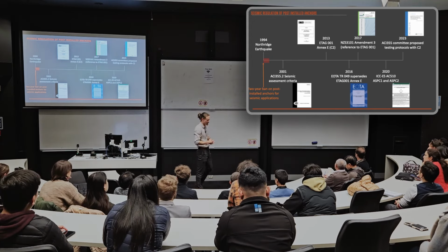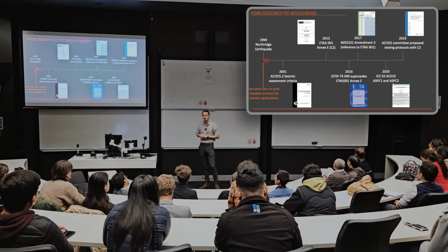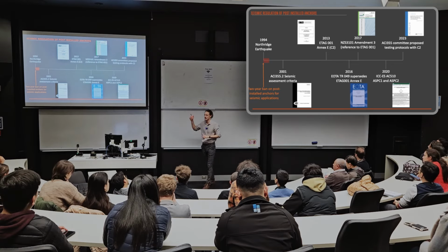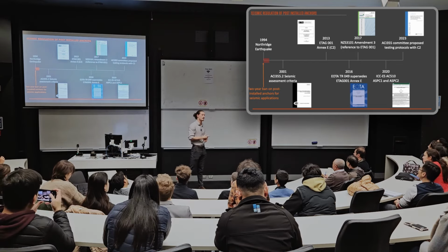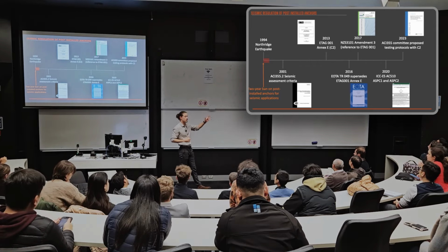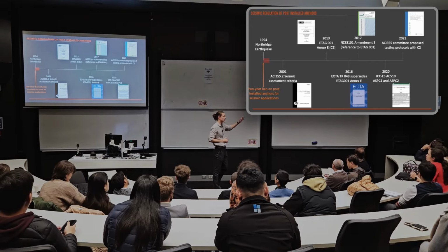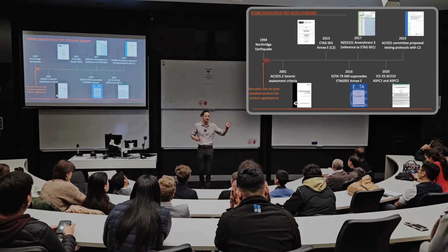2017, this is when New Zealand came to the party, right? Amendment 3, and this is when we started using C1 and C2 capacities in our designs. I think it's interesting to note that this is not where it ends. So this is still very much a developing part of our industry. In 2020, the International Code Committee released their acceptance criteria for post-installed anchors in cracked concrete under seismic loading. ICC, for anyone who's not particularly familiar, is the independent code assessment organization primarily in the US, or they do work in other countries as well.